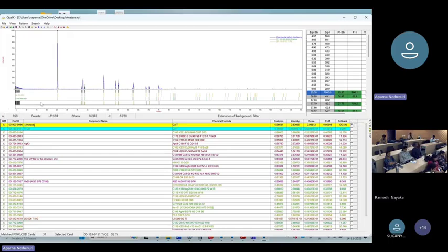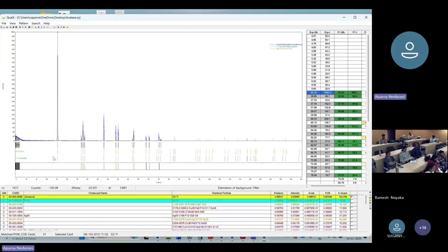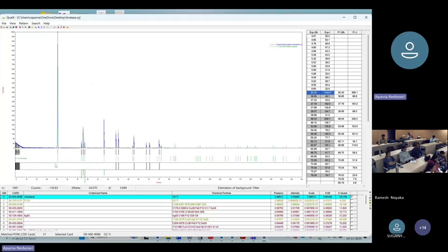Once you select it, can everyone see this? Is it very clear to everyone? Now which one have we selected? We have selected NTS, right? This one. Now you can see that this is the 2 theta position at which your peak is there from your sample, which is black in color. And this is the 2 theta position at which a peak is present from the card that I have selected, which is NTS over here.